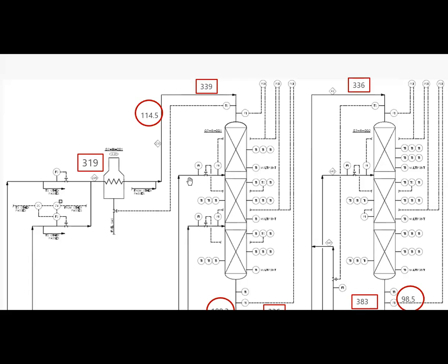In the reactor, here in the lateral, if you see it, after bed 1 you see another arrow entering the reactor. This is a quench. And as you can see, this is a control valve, and it is a temperature control valve. You can see here a TC, we saw in the other online session about PFD. It's a temperature controller that goes to this valve, opening or closing this quench valve at the outlet of the first bed. Then you have the second bed, the same, you have another quench.